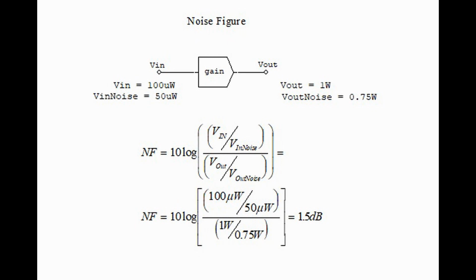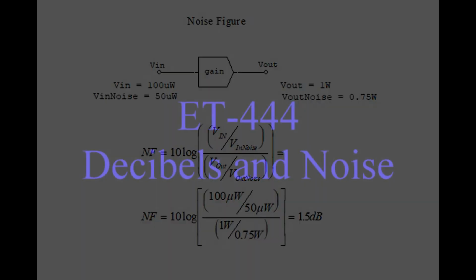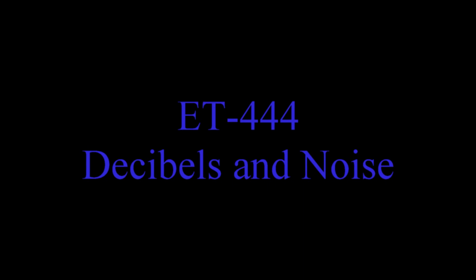In this case, the noise figure number should be very low because that indicates that we have controlled the noise when we went through a large stage of amplification. Those of you who started building the radio, you will notice that on several occasions it will ask you to measure the gain of a stage of amplification, such as a transistor. In that case, always convert the gain to decibels, like we've learned in this chapter, because that's the best way to deal with amplification.